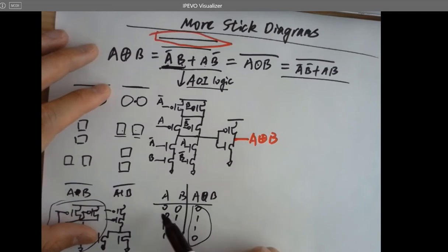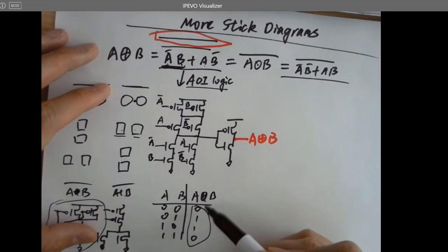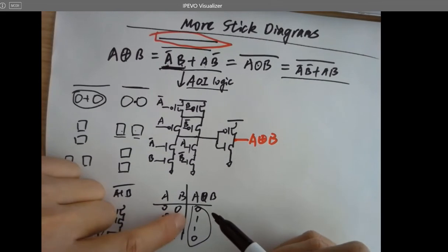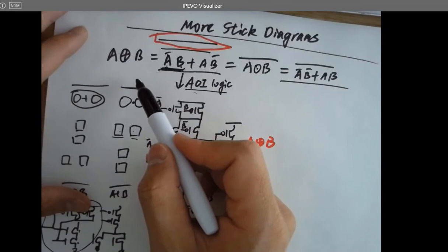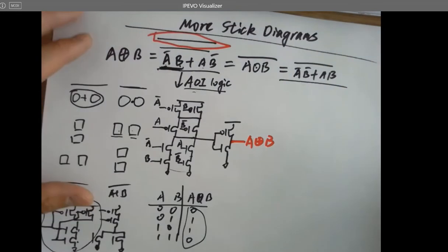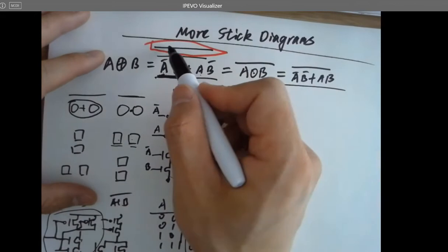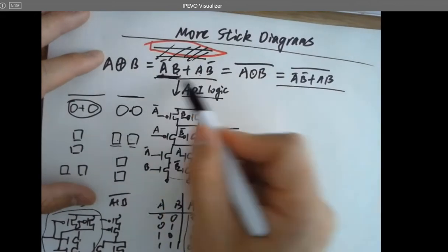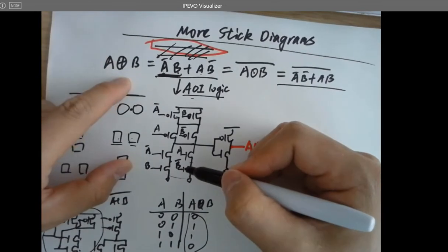You just verify all these input combinations. If you get exactly the correct result in the truth table, then definitely this guy is a XOR gate. So that's when you just directly use this logic expression to find out the AOI logic for the XOR gate.